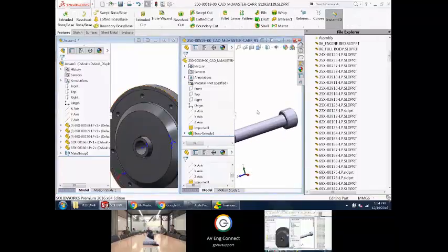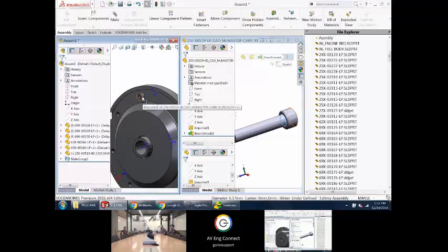When you are in the same screen, meaning the assembly screen, and you want to do SmartMate, you need to hold the Alt key down. But if you're in separate windows, and I grab a circular edge and drag it to another circular edge, I can do a SmartMate without holding down a hotkey. And so that's typically how I'll put in a bolt. I'll just open up that bolt, bring up the assembly I need to put in, and just start putting as many bolts as I want to in the holes.